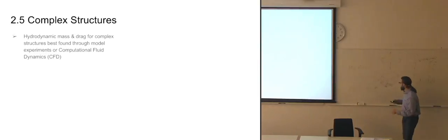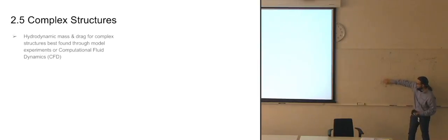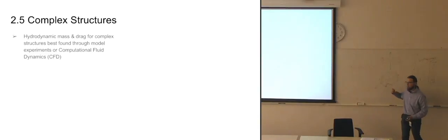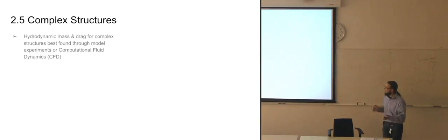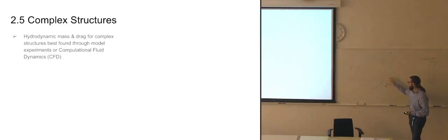It of course means that since much of the water has the ability to pass through parts of the ROV, you won't get as much of a cross-sectional area to put in for your added mass and everything. But still, that's basically the only way to simplify it, is to just look at it as one block instead of looking at it as it really is.